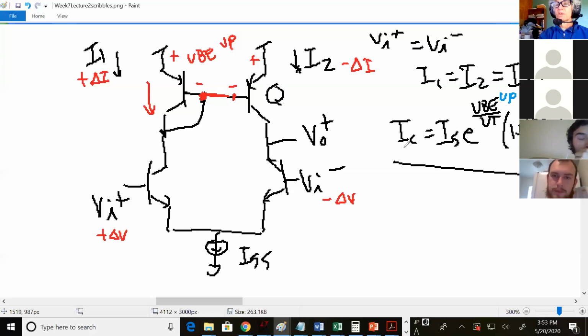But what happened to the current? It went down. So it has no control of VBE, and this smaller current is being forced through this transistor. So something else has to change here in order to turn the current down. So what changes? Could I guess VCE? VCE changes.